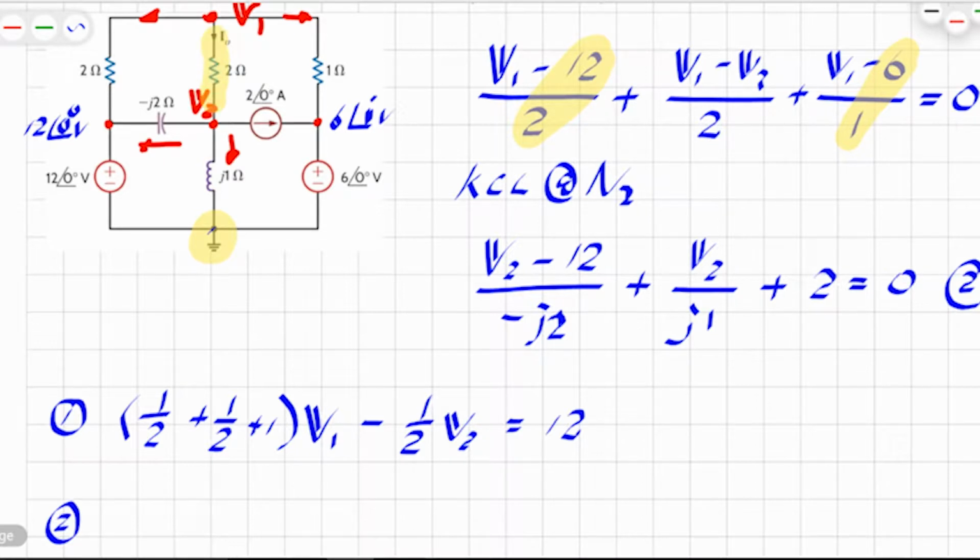There's a current coming out of this branch, so there should be 4 branches. And as we assumed, the I0 is coming into the node. So I'm going to add this current, because I assumed that all the current coming out is positive. Coming in should be a negative.